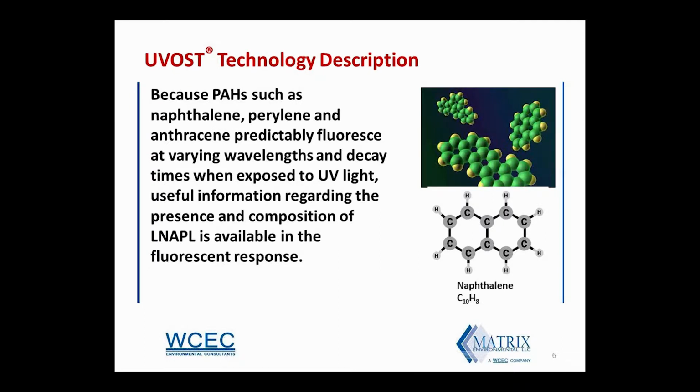The fluorescent responses of certain PAHs are predictable in terms of the wavelength and decay times, so this information can be used to not only identify the presence of LNAPL material, but also tells us something about the composition. And we'll show this in greater detail in a few minutes when we look at some waveforms and logs.